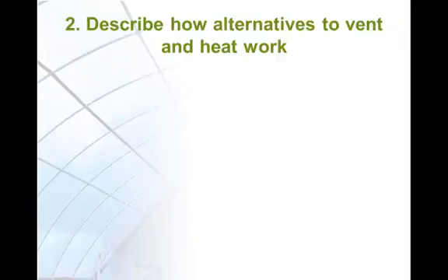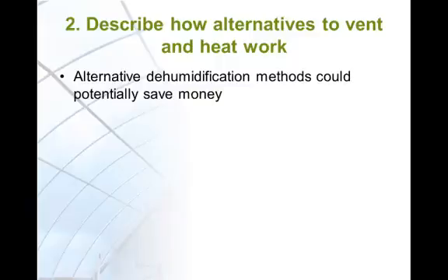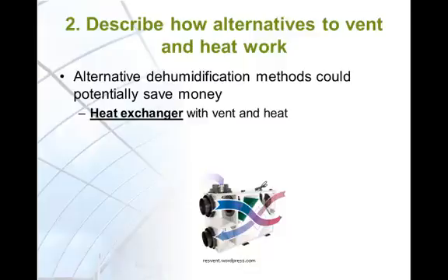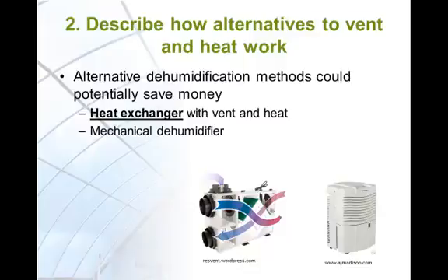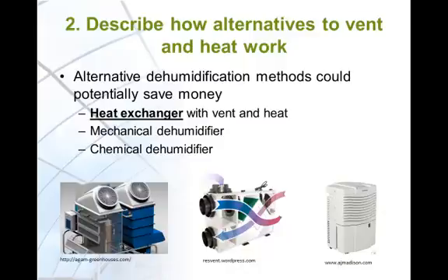We will now discuss 3 alternative methods of dehumidification. The reason for a discussion of alternative dehumidification methods is these alternatives have the potential for cost savings. The addition of a heat exchanger to a conventional vent and heat operation, the use of mechanical dehumidifiers, and the use of chemical dehumidifiers.